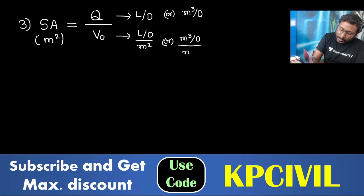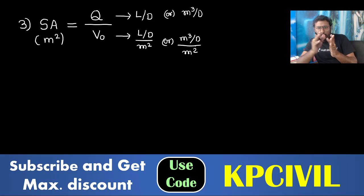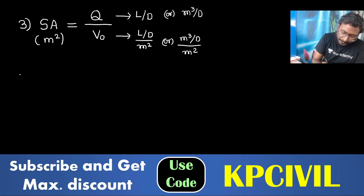Discharge may be considered in liter per day, so you take V0 in liter per day per meter square. Or discharge may be considered in meter cube per day, and you take V0 in meter cube per day per meter square. Depending upon the units, unit conversion is very, very important. Surface area is equal to Q by V0. After getting the surface area, dimensions are needed.